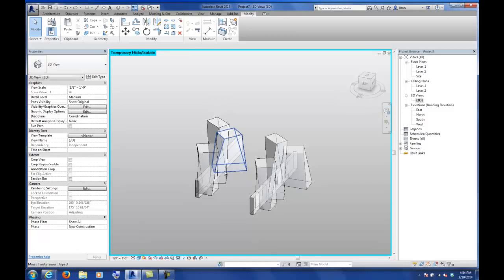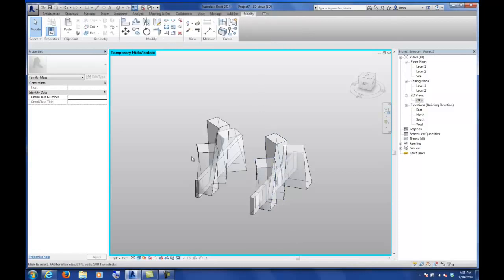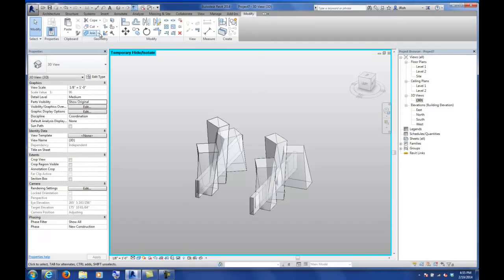So what I did is I made, in the massing environment, I think everyone saw that, where I just made a rectangle and extruded that up as a solid. Once it's a solid, we can now use this cut option, which is under Modify. So under Geometry, there's Cut and Join. Kind of works as your Boolean unions and Boolean difference, kind of like in Rhino.